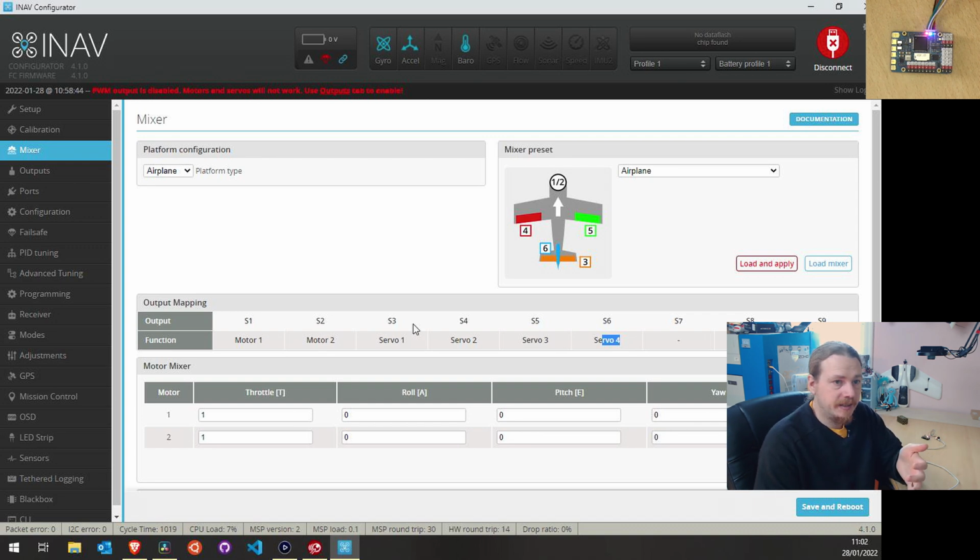If you use any ADCs, like for an analog airspeed sensor, for example, also just make a note of that. And that way we don't have to dive deep into the plane potentially to try and see what we've wired stuff up to. We can just set everything up on the ports based on what we've written down in our notes. So it just makes life easier. But just remember that as you make your plane, and I will see you soon.